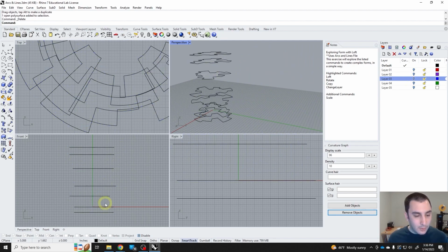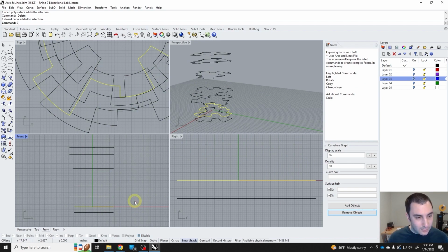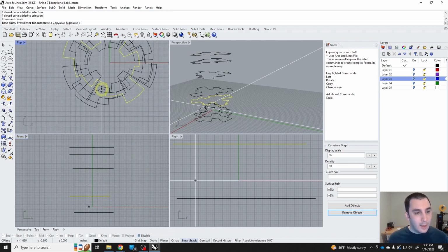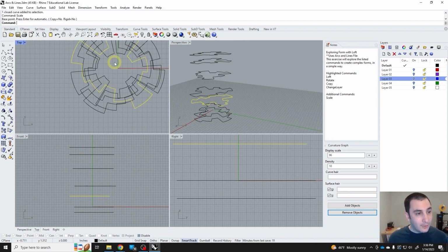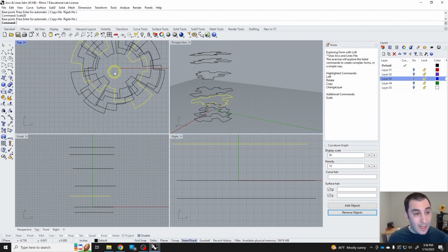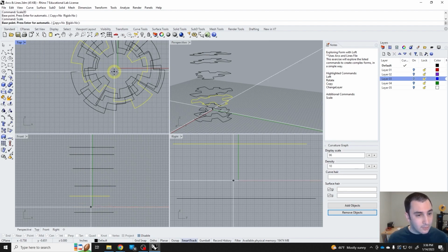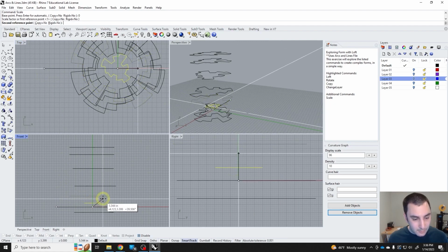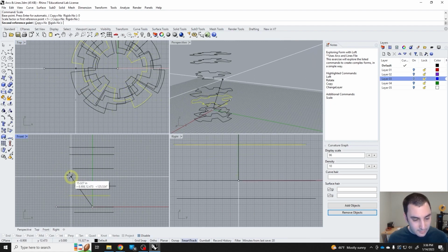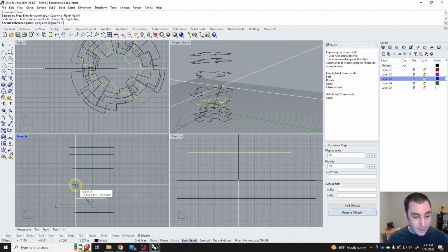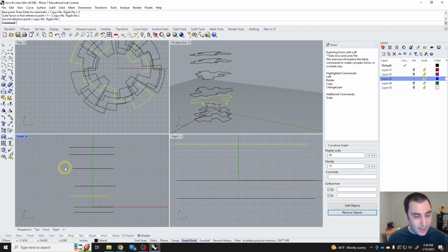First, I'm going to start scaling these a little bit. So I'm going to go ahead and scale these middle 3. And we'll do scale, again, from the top viewport. Actually, I'm going to do a scale 2D, because this is what happens if we don't. If we do a scale, it's 3-dimensional. If I reference my origin and scale it, it's going to move it in the Z dimension, because we're scaling it from a location that has a different Z location.